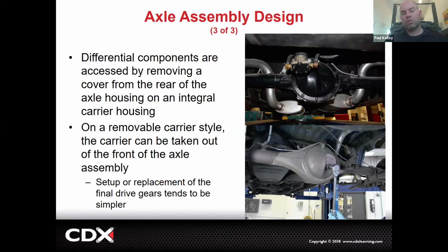Well, actually not really true. There's always going to be a fill plug and a check plug. Generally, there's a drain plug, but on this style, there may not be. If this style you had to drain this, you actually have to unbolt this cover right there, and then you have to replace the gasket and reseal it and all that type of stuff just to change the fluid. It is kind of ridiculous. But on a lot of the new ones, they've put plugs on both styles.